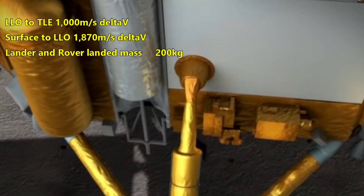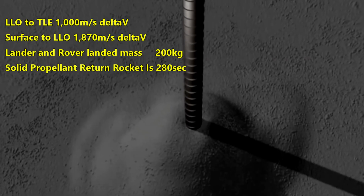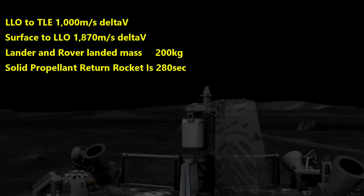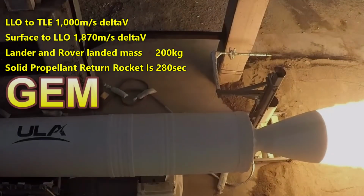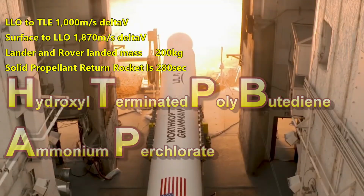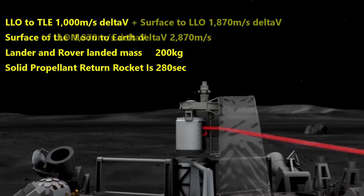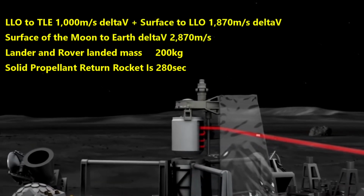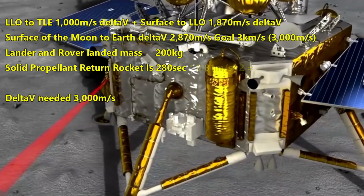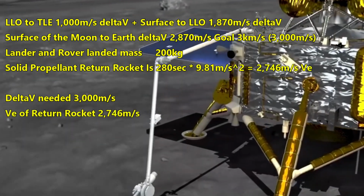Let's use a solid rocket motor with a specific impulse in vacuum of maybe 280 seconds. This would be a high-performing but realistic goal, and is achieved by the GEM solid rocket motors, using hydroxyl-terminated polybutadiene-bound ammonium perchlorate composite propellant. Adding our delta V to get off the moon and past L1 gives us 2,870 meters per second. Let's round that to 3 kilometers per second to have a safety margin. We turn 280 seconds into exit velocity and get about 2,746 meters per second VE.